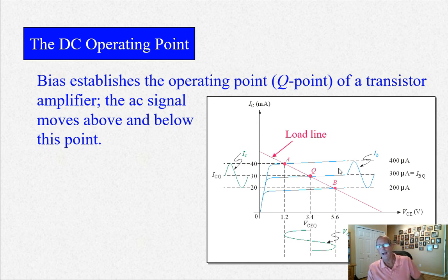And I like this graph, and I like the next one we'll look at very much because, first of all, it shows this load line. It's called the load line. And this Q point here is sort of the transistor's happy place. This is where it wants to operate. This is the quiescent, Q stands for quiescent operating point of the transistor. That's when, theoretically, in an amplifier, nothing's happening. It's no signal. It's silence, if you will, for an audio amplifier.